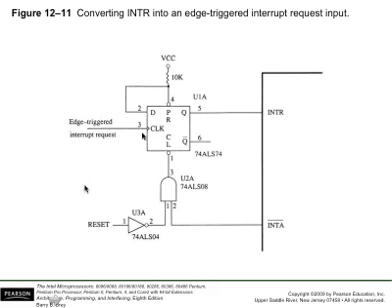So whenever an interrupt happens, there's an edge. And we use this as the clock input to this D flip-flop. So whenever there's an edge, that is to say a clock pulse coming in, this D flip-flop will update its own state. That's essentially going to load the value of D to Q and also update Q bar.